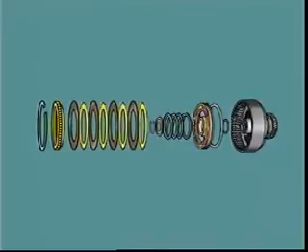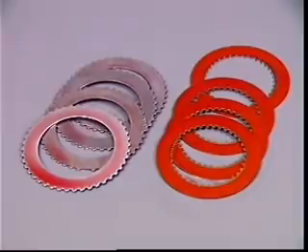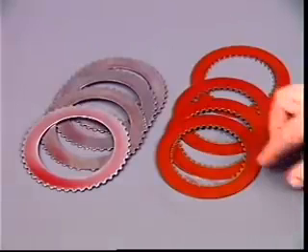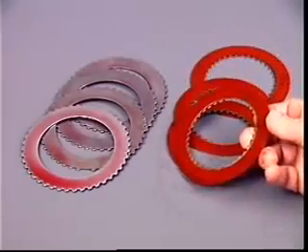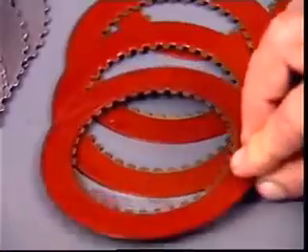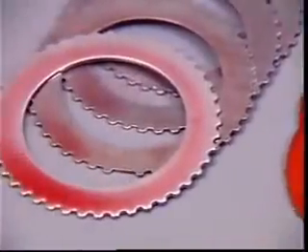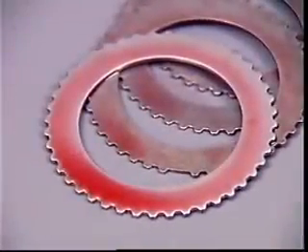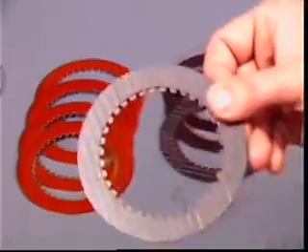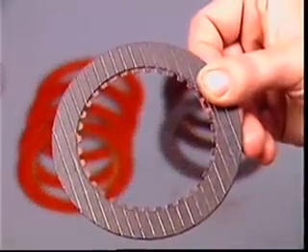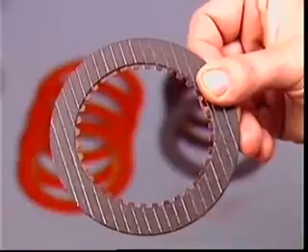They have a set of driving plates and a set of driven plates collectively called a clutch pack. Both sets may be spring steel, but one has friction material bonded onto both faces. And since they operate in the transmission fluid, they are called wet clutches. The friction material may be plain or grooved. Grooving allows for fluid to escape from between the plates when the clutch engages.